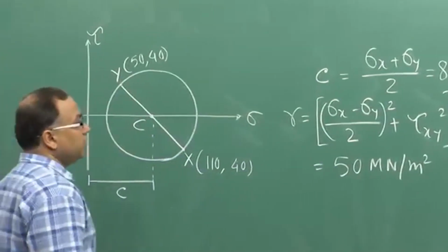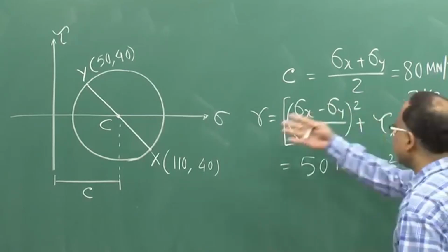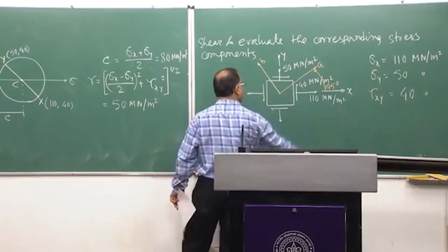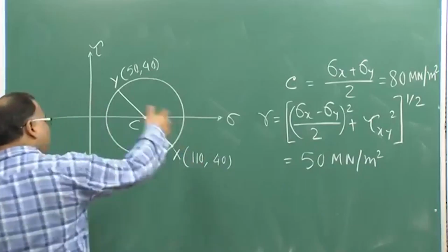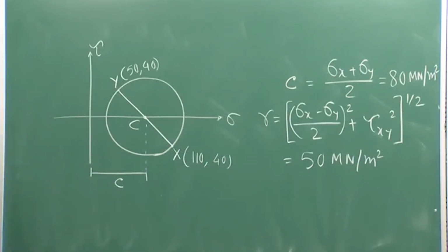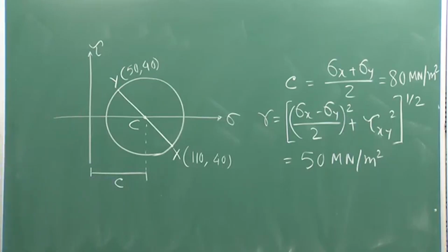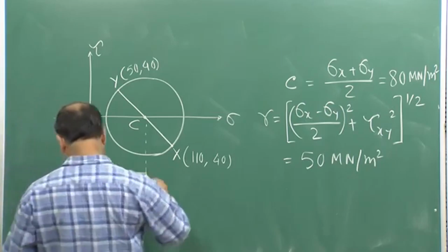your AB, if you look at, this is your physical plane, this is your stress plane as per our definition. So, in the physical plane, the angle between x axis and A axis is 45 degree in the anticlockwise rotation sense. Okay. Therefore, I can locate here the axis, basically A plane and B plane like this.